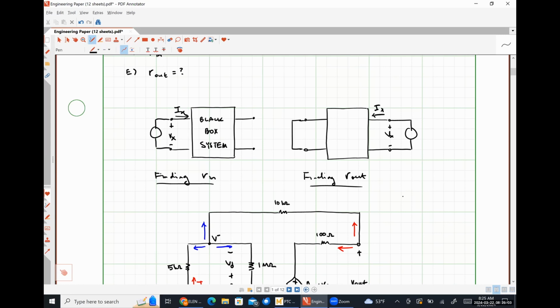When you're finding the Thevenin equivalent resistance of a network containing a dependent source, we needed to make sure that we were looking at a dead network. We could go that route, and there's nothing particularly wrong with it. However, there's an alternative method for finding the Thevenin equivalent resistance, which I believe you're familiar with because I asked you to do it on homework set number 1. That is simply to take the ratio of the Thevenin voltage to the Norton current.